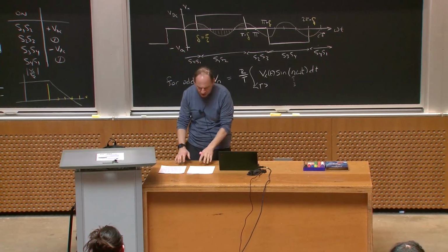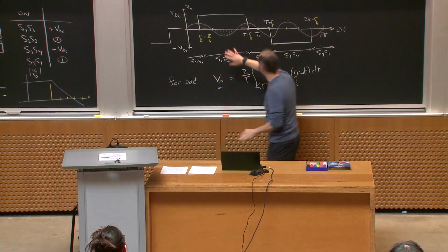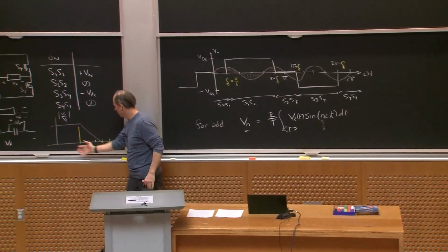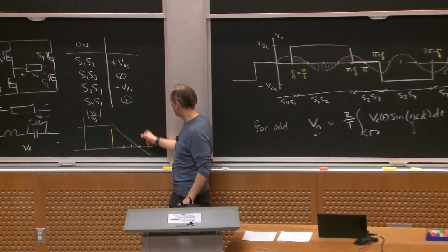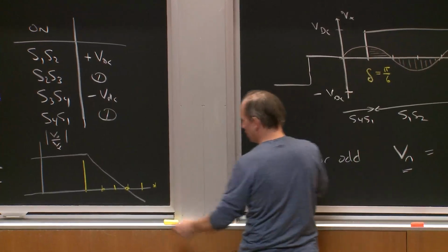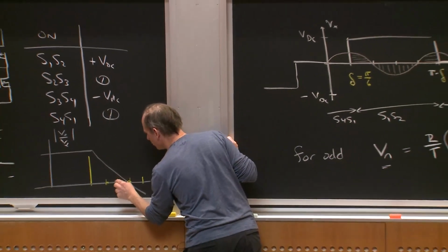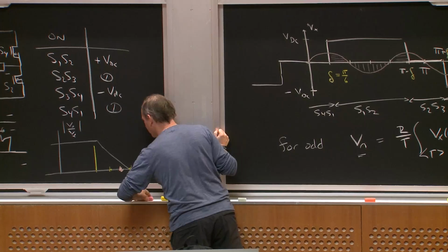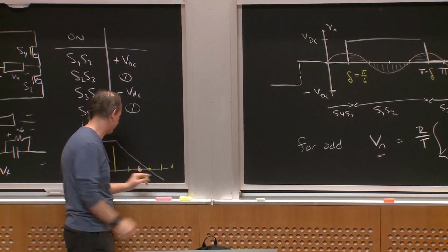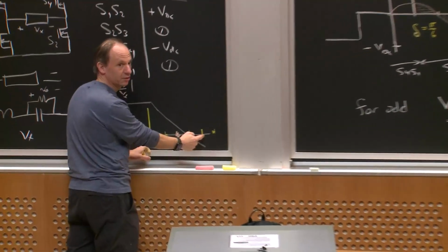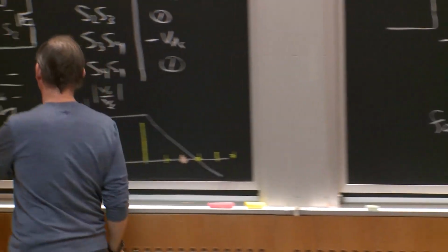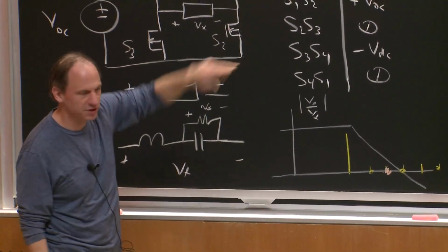Okay, so how might I go about it? Well, a principal reason I did this was because I said, okay, I've gotten rid of the even harmonics, but I've still got to worry about 3, 5, 7, etc., right? If I picked my angle just this way, I would pin 3 to 0, so that would kill the third harmonic. And that means, since the fourth is gone by symmetry, the lowest I have to deal with is fifth. Now I'm starting to get some nice space here, and that lets me get much more pure filtered waveforms at the output compared to this kind of pulsy shape I'm generating.